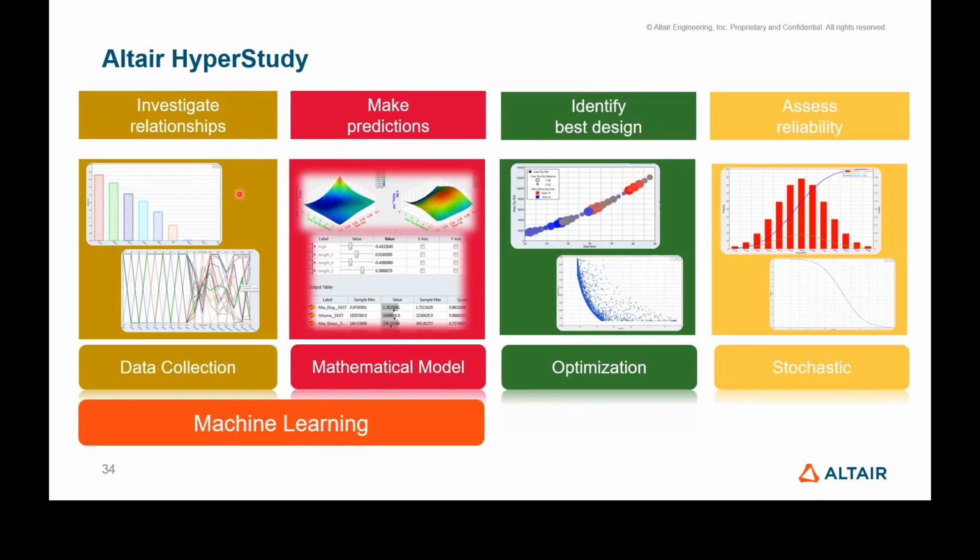Essentially what happens is that you interface Feko with HyperStudy, which is already done. So basically you import the CADFEKO file into HyperStudy. HyperStudy imports all the variables that we defined in CADFEKO for a parametric model. So you can pick and choose which parameter you would like to optimize for your gain or S parameters or whatever quantity you would like to optimize for an antenna.